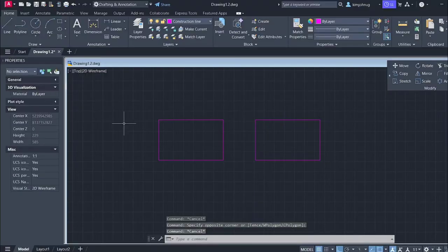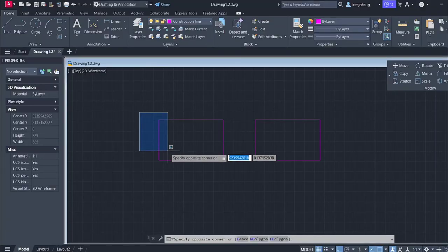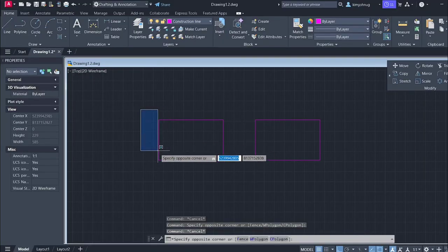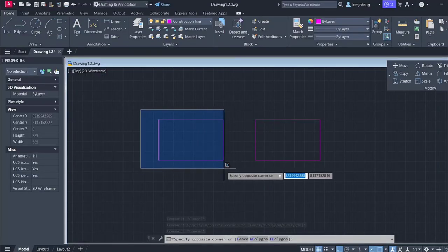So let's try it on these lines which are not joined. Left to right, it selects a complete line. If you select an object, for example, just select a complete line, it selects it. I see. Initially it wasn't complete, so if I complete now, it selects the line. So if I want to select the horizontal lines, it can't until I complete them.